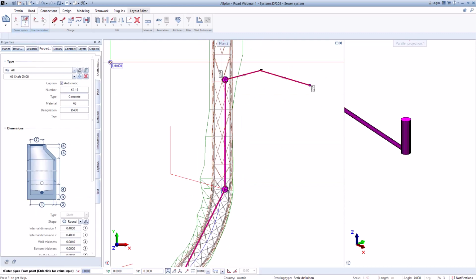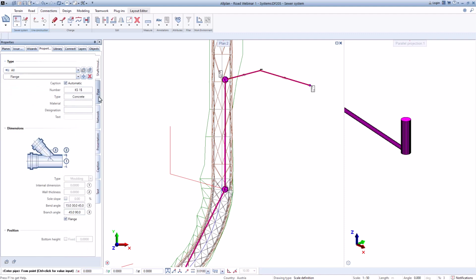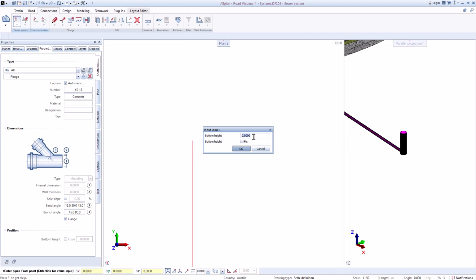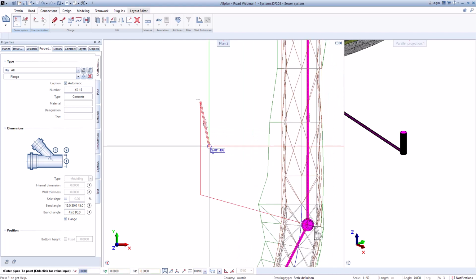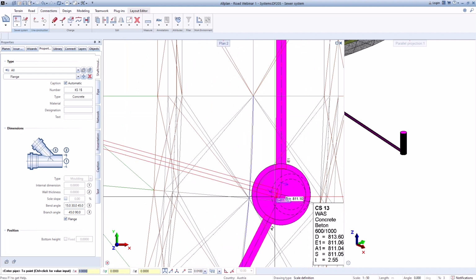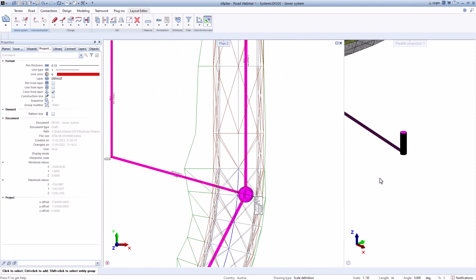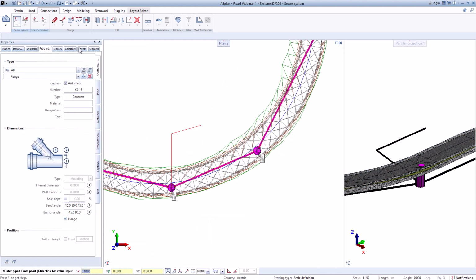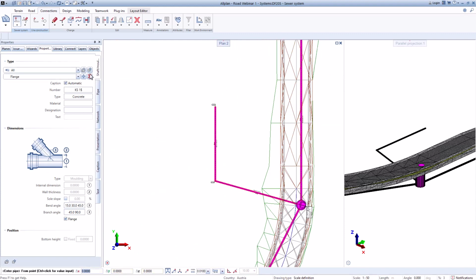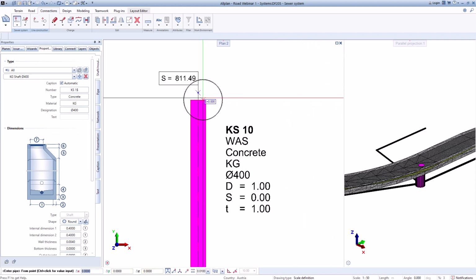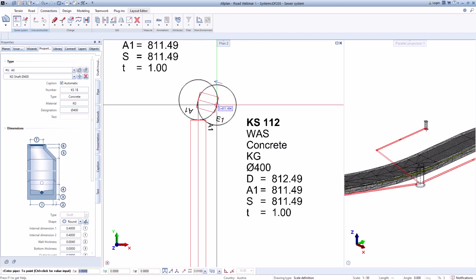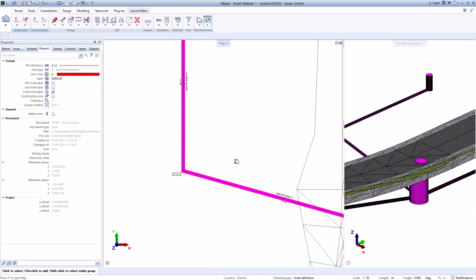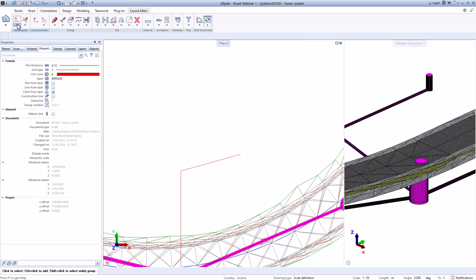Now we will connect the second house. Again, choose a flank that you can use a pipe with the different angles. Again, Control to open a window where you can enter the height of the start point of the pipe, and here it ends in the shaft. Okay, that's the second one. Also here we have to add a shaft. So Control click, and it will put it at the bottom end of the pipe. Okay, you see here 2% inclination, and we go now to the second one.